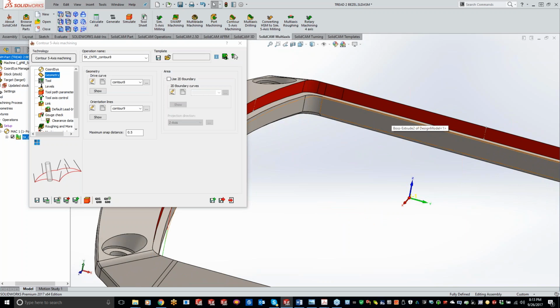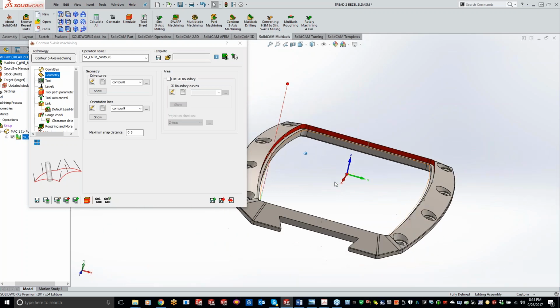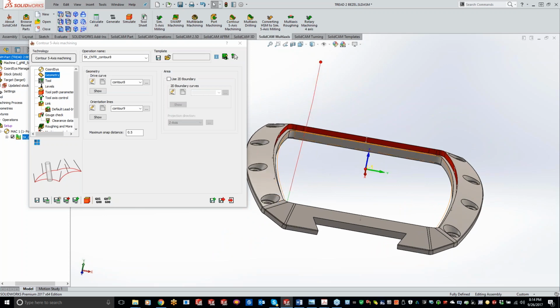And you guys can add these at a different angle to achieve a certain result. Maybe you want it to rotate over more on one side versus the other side. That's what we're going to be doing in our next part here. We can change the angles of these so it's moving around. That's more or less for doing the trimming or a chamfer around the outside of a part. Or maybe you've trimmed the part and then you put a little deburr operation on there, or a chamfer going around the outside edge. Okay, so that's using it on the inside.